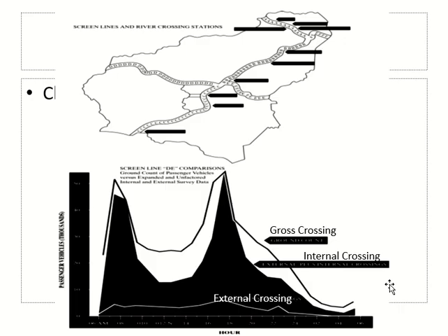Okay, so in the screen line count, we are interested in how many people are crossing the screen line, going from one area, one zone to the other zone. So in this figure, you see 2 areas, and between the 2 areas, this is a river. So they made the river as a screen line, although it's not a straight line. And the reason is that crossing the river will be at fewer points as compared to crossing from other highways or streets. Okay, so you make the river as a screen line, so the crossing points are minimized,